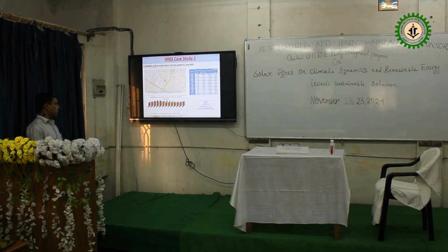Raw data is required. So we have planned within this Homer study, for the energy development, that the geographical location we have given, and based on that, what data depends? Data of the solar radiation, the wind availability, as well as the temperature. This is based on the annual average, 10, 20, whatever you will fix in Homer according to it. That is also linked to the demand. NASA also provides that data.